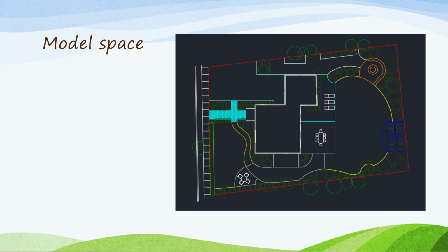The circle tool is used to create circles of various sizes and was used on this project to create the proposed bushes and fire pit. The arc tool has multiple options within the tool. However, for this project, we used the 3-point arc tool. This tool works by selecting your first point, estimating the middle point of your arc, and then making your end point. On this project, this tool was used to create the curvilinear lines, such as the gravel path.